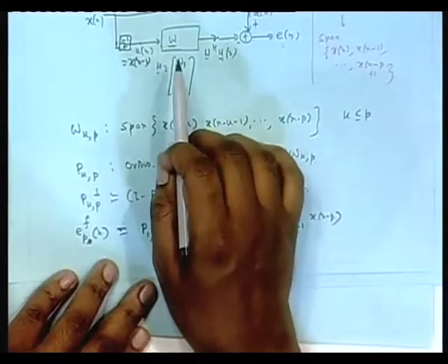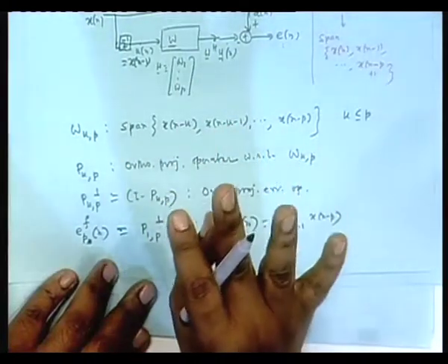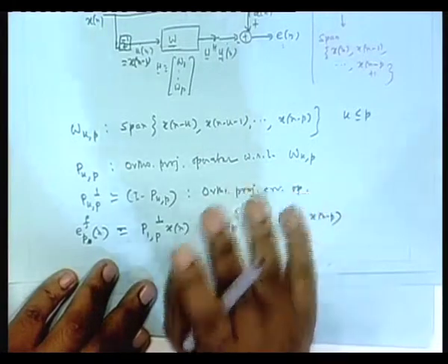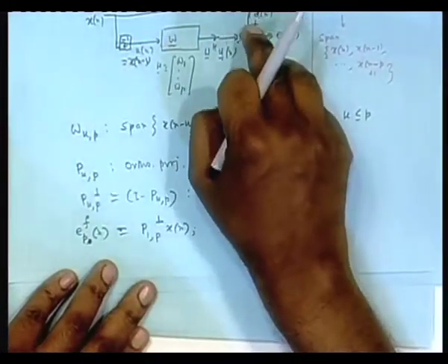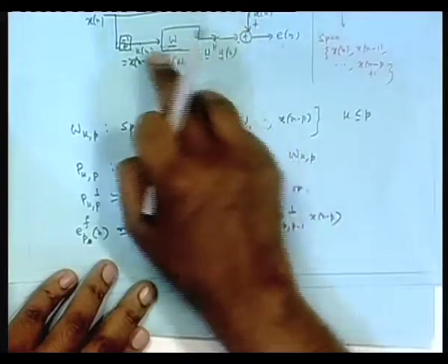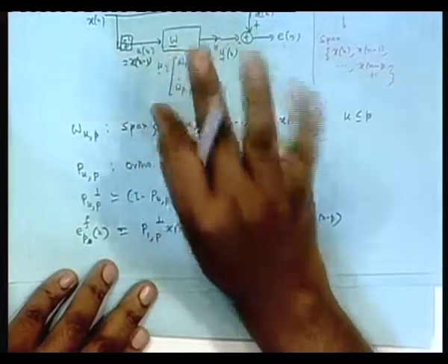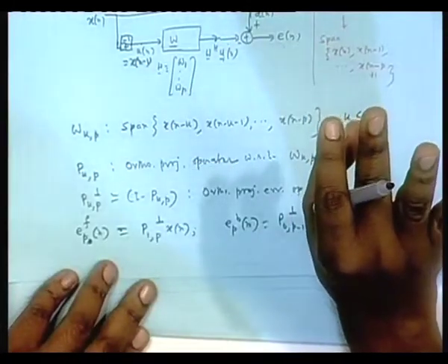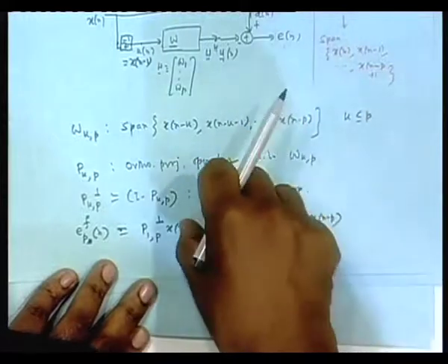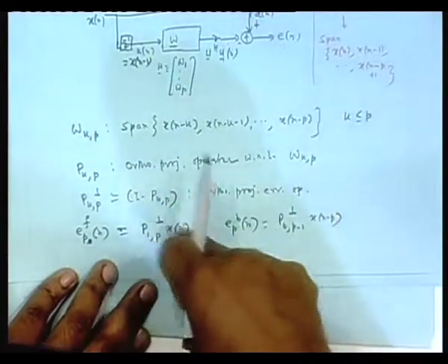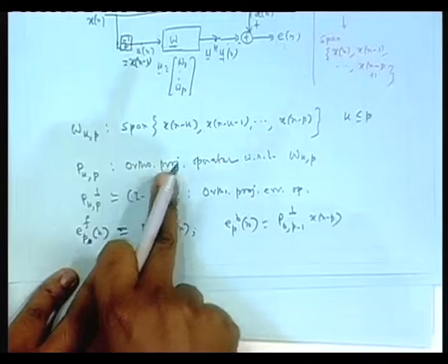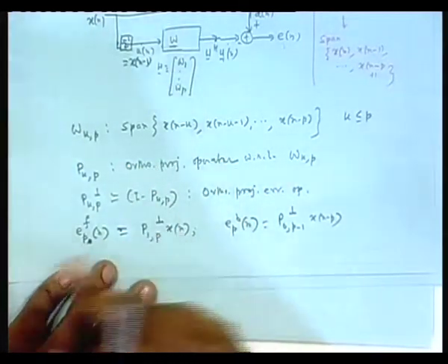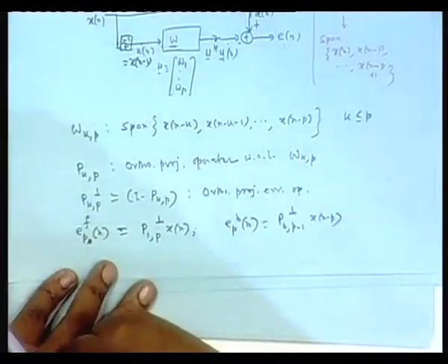But the linear combiner coefficients we already know, because of stationarity they are independent of n, isn't it? For any general case, you give a sequence here and you give some sequence there, you get a linear combiner coefficient or filter, and those are independent of n. That we have seen because of stationarity, we are also assuming the WSS thing. That means what is this quantity? It is xn minus a linear combination of past terms xn minus 1 to xn minus p, but the combiner coefficients are constants independent of n. That quantity I have to find its variance.